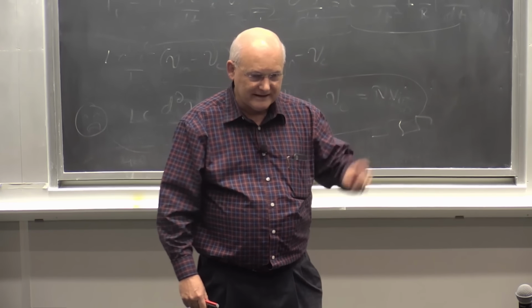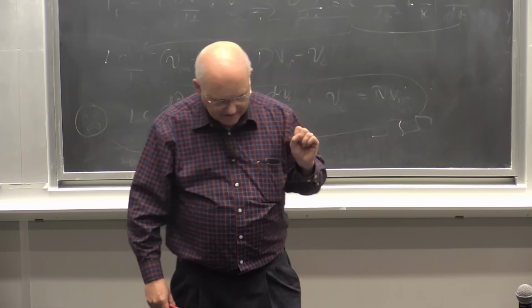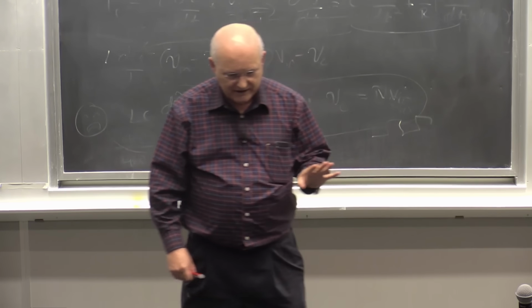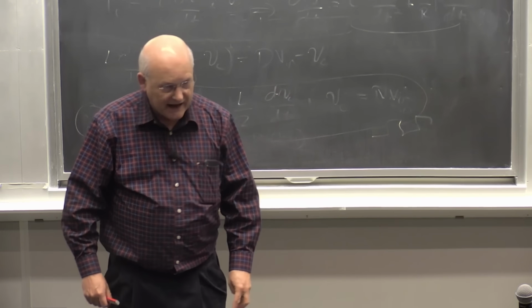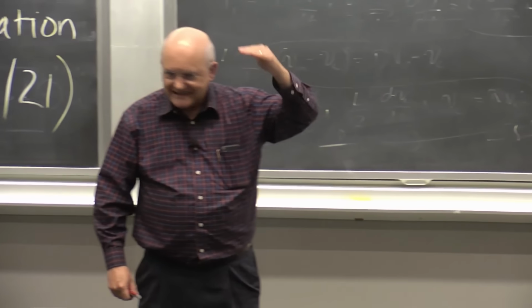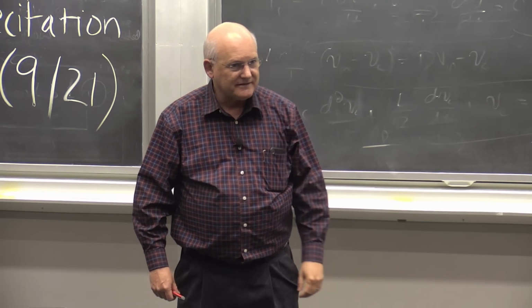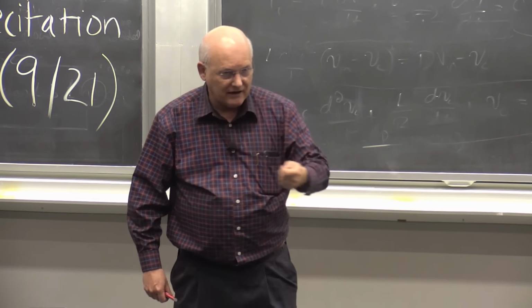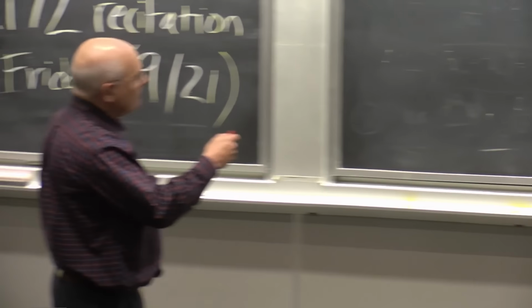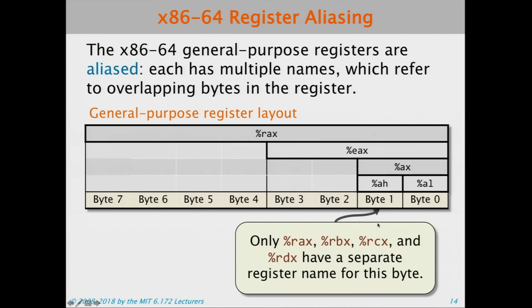And from there they had some more growth pains and went to 64. Those were two separate things. And in fact, they did some really weird stuff. When they made these longer registers, they have registers that are aliased to exactly the same thing for the lower bits, so that they could address them either by a byte, the lower and upper half of the short word, the 32-bit word, or the 64-bit word.